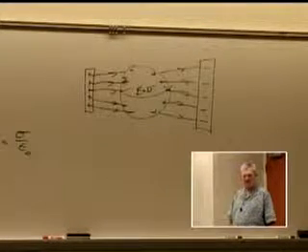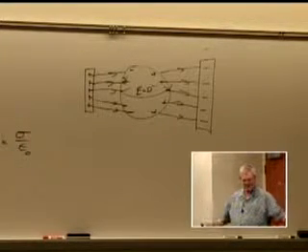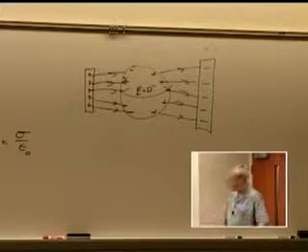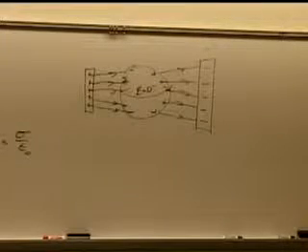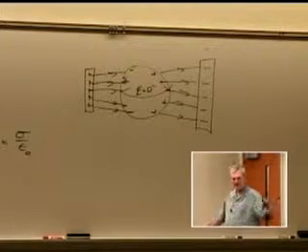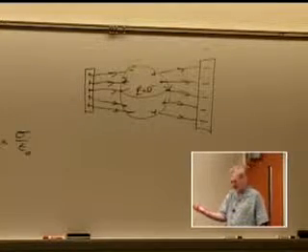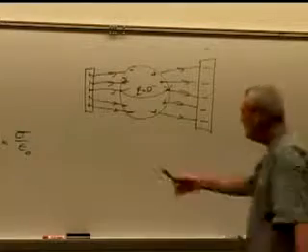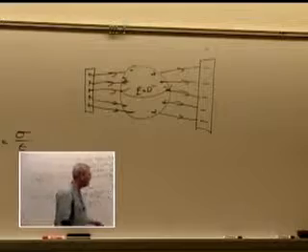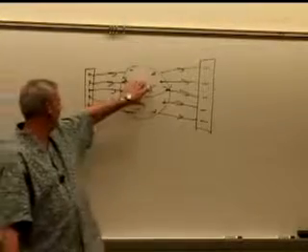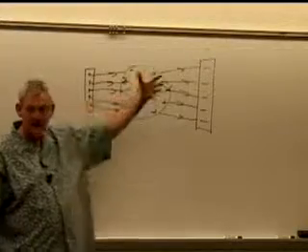What would happen when Mom would turn on the mixer? You get all this interference, and you couldn't see Mary Ann anymore, until she turned off the mixer. That's because the mixer created an electric field that was going out, and it was interfering with the circuitry of the television. But with this shielding, if you've got a good shield around all your circuitry, in other words, you put all your circuitry inside this little ball here, this conducting ball, not a wooden ball.